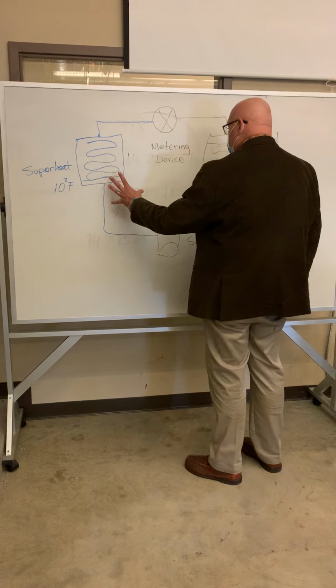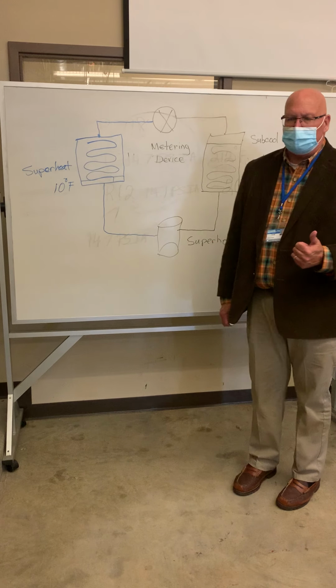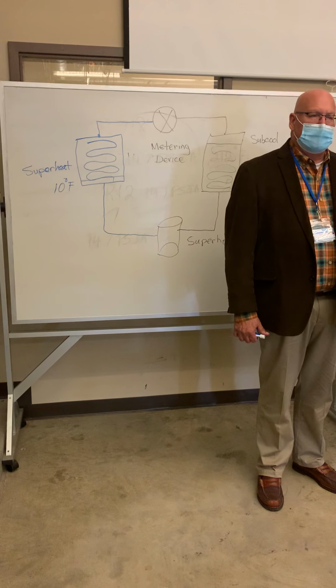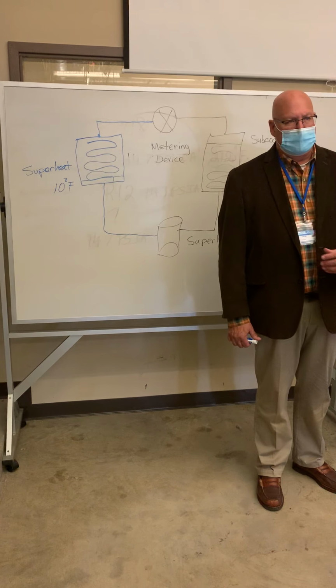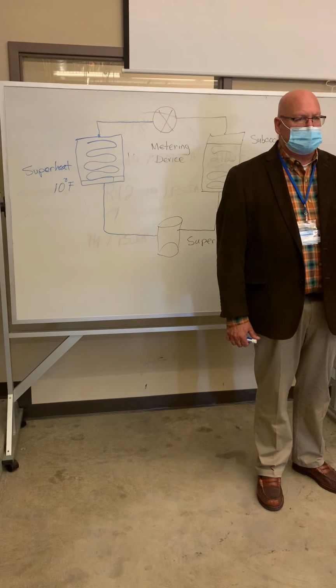So that's what occurs here. So it's gas in the compressor, and it's gas out of the compressor. Gas in, gas out. If liquid enters the compressor, it's going to cause the compressor to slug and to break its valves.